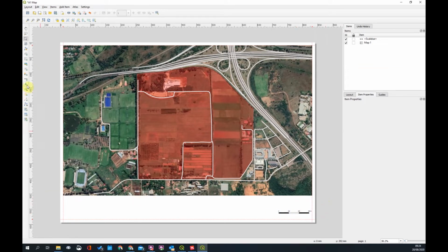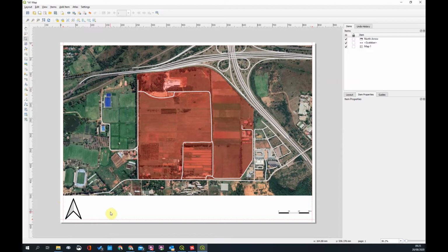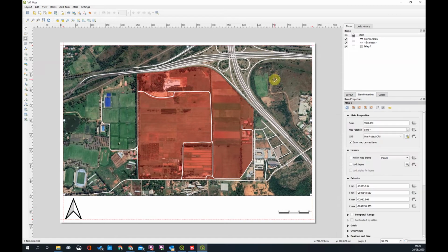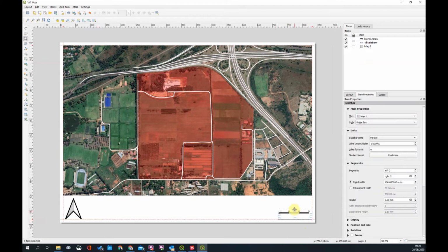The next thing I want to introduce, and you can see these all have labels inside. You can add a legend, so we'll get to that in a minute. So I'm going to add a north point, and I'll put the north point over here somewhere. I can scale this up right to there. Maybe make this a fraction smaller. Okay, that works. So north is always up, and this is 300 meters. The software, I understand, reads the size of the map and sets up the map accordingly. Okay, so I'm happy with that.